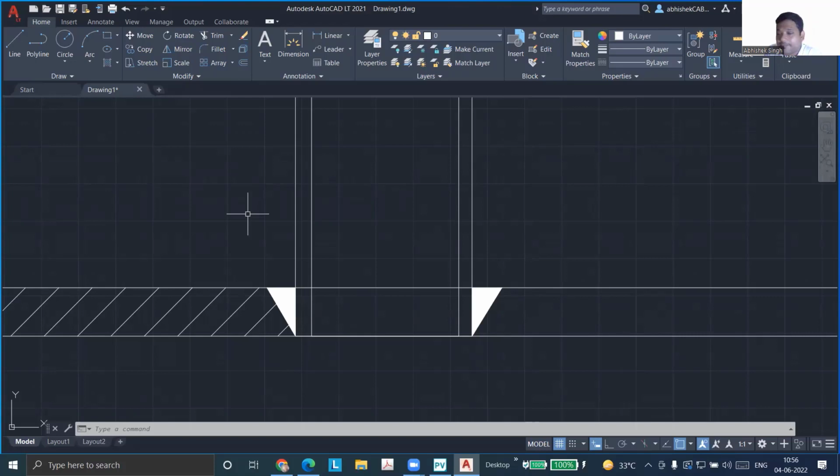Because if we do dye penetration, we provide some liquid which is very penetrating, and then we spray white. If some cracks are there, the liquid will go inside, and you will see a clear-cut pink line wherever the cracks are. So it's a yes or no kind of thing.